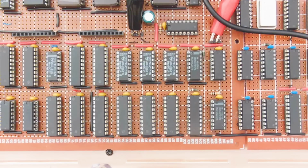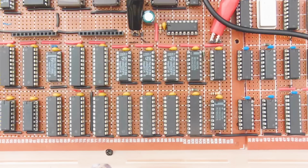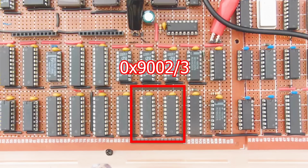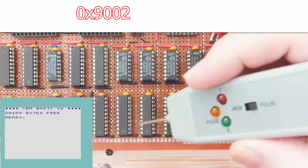So, how does Choplifter work? Let's take a closer look at how the VIC registers are programmed. First, how come the display is 22 by 23 characters in the first place? I've broken out the 2 VIC chip registers here located at 9002 and 9003 hex. In standard mode, where we run BASIC, let's see what's going on with these registers.